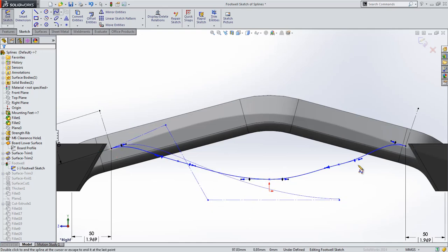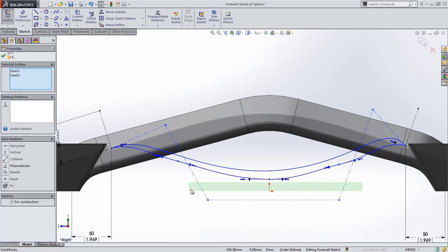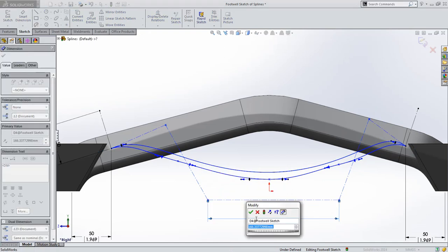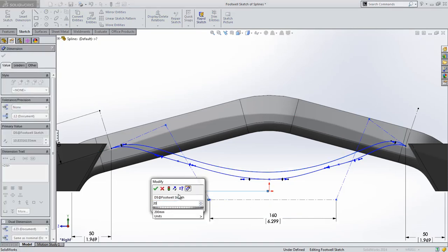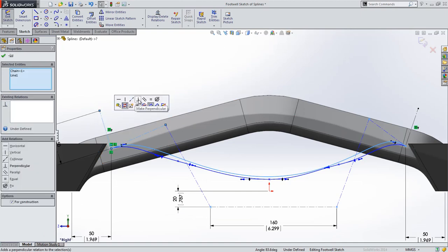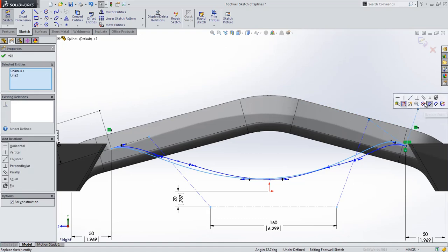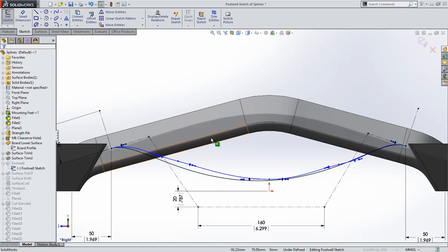Instead of individual spline points, which need to have the curvature and magnitude controlled, they are simply placed with construction lines. These lines can then be further defined using simple and familiar sketch relationships and dimensions all users are familiar with. As all the required relationships and dimensions are added, it becomes fully defined quite easily also, letting us know it will be fully controlled by any upstream design changes.